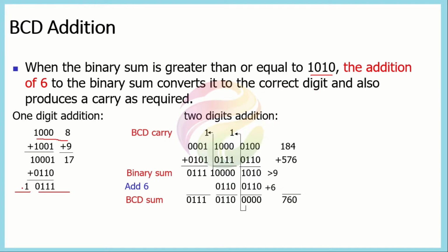And when we are representing this in BCD, because this is the carry out, we will also represent 3 zeros here. So it is actually 1 and 7. So we will be separately representing the 1 term and the 7 term. And how we do it, we just add a 6 to the result if the result is greater than 9. Now we will see 2 different numbers.